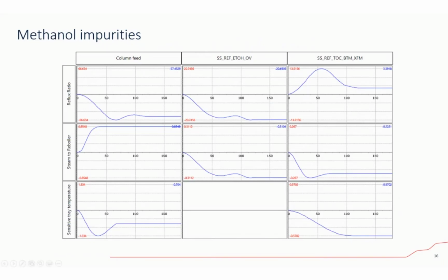In any case, of course, we built what we call a steady state soft sensor. So it's based on the changes on the inputs to the calculation. If you were taking samples, then you would have a little bit longer time to steady state, because the dynamics inside would make it a bit longer. But for control purposes, this was long enough for us to keep good control. So that was the time to steady state, around 3 hours, as it says here.